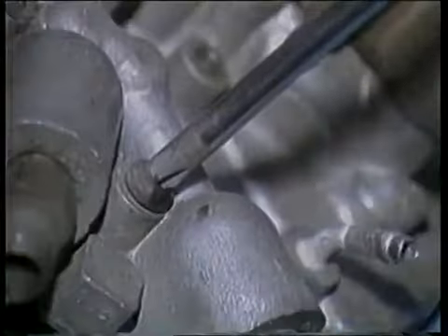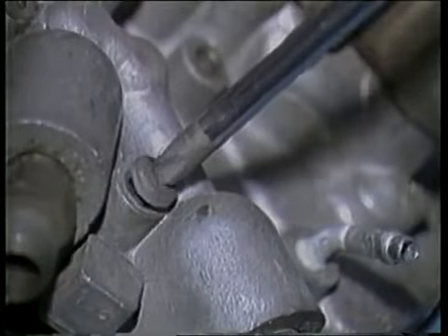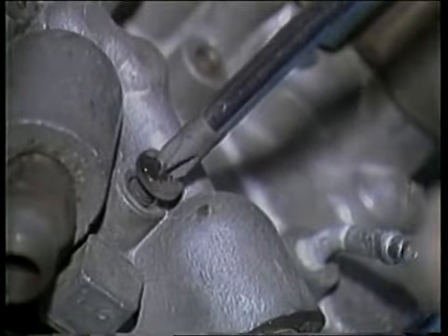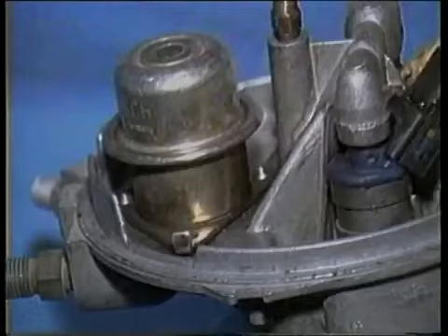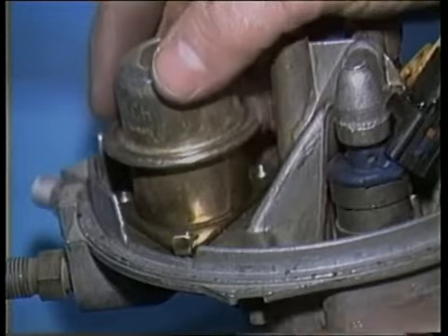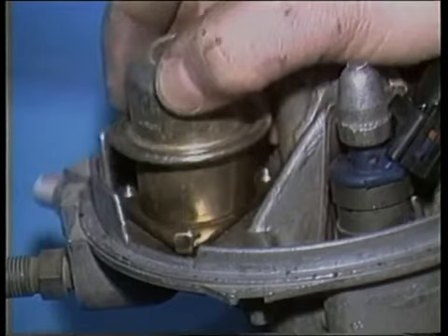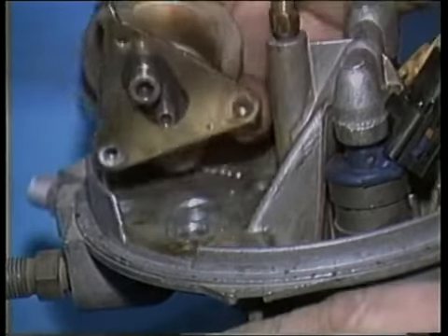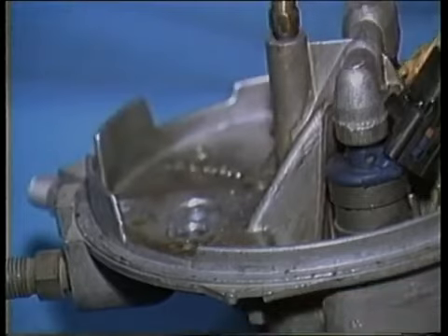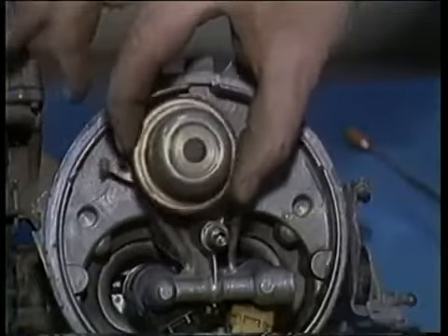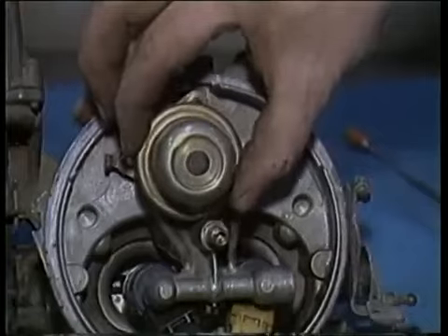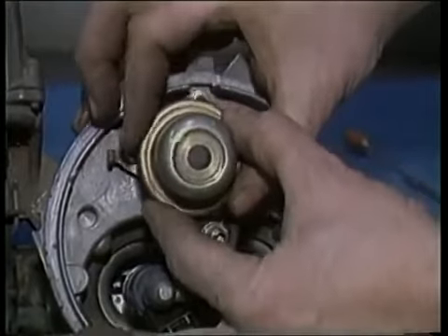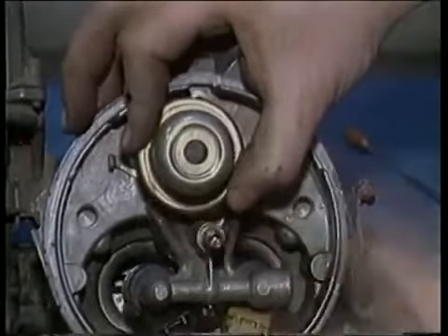To service a throttle body pressure regulator, you sometimes have to remove the throttle body from the engine to access screws from the bottom of the body. This will allow you to lift off and replace the pressure regulator. With other designs, the TBI pressure regulator can be serviced with the throttle body unit on the car. Make sure you have the correct replacement pressure regulator.